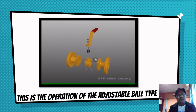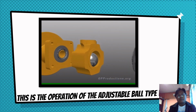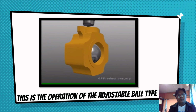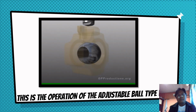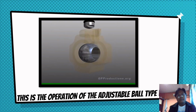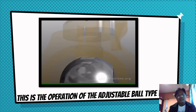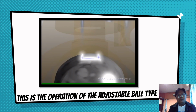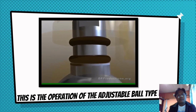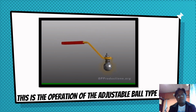A ball valve consists of many different parts. The main body, which houses the valve, utilizes an array of other parts in order for the valve to function properly. The apparatus that controls flow is a sphere or ball. The ball has a hole or orifice machined through its center. The stem attaches the ball to a handle. There is a slot machined into the top of the ball. The stem fits into this slot and is bolted to the handle on the other end. As you turn the handle, it turns the ball to either open or close the valve.